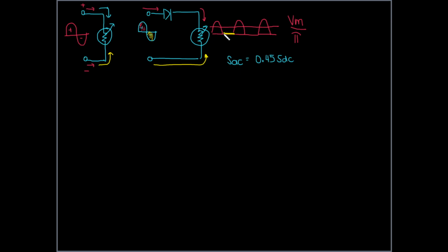And this is the reason why, because we implemented half wave rectification using a single diode. There is a little bit of modification basically to clear out this negative alternation here, and we can make use of an instrument rectifier, but I will discuss that in my next video.